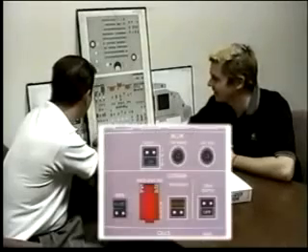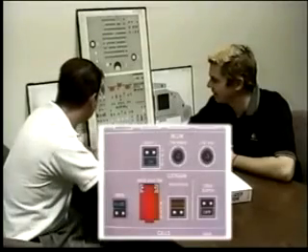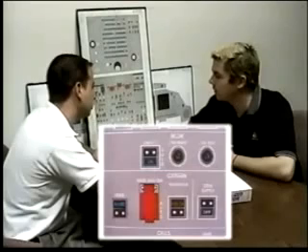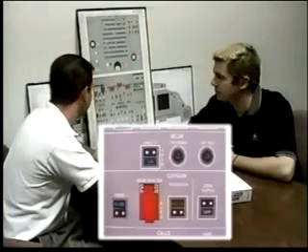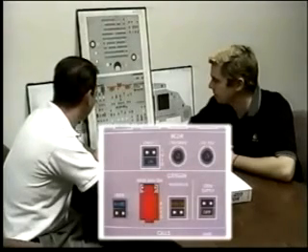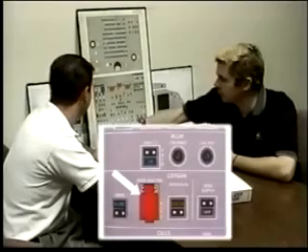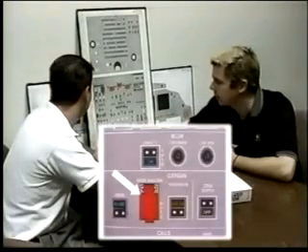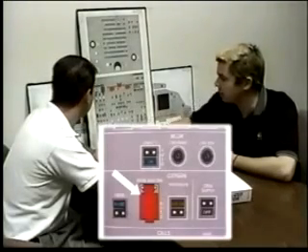On the oxygen panel, when will the passenger oxygen system deploy? Whenever the cabin altitude exceeds 14,000 feet. Could you manually deploy? Sure, I'd lift the switch up and then select the button that's underneath there.